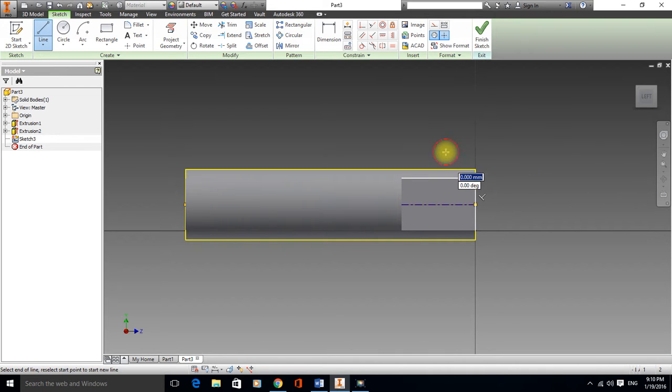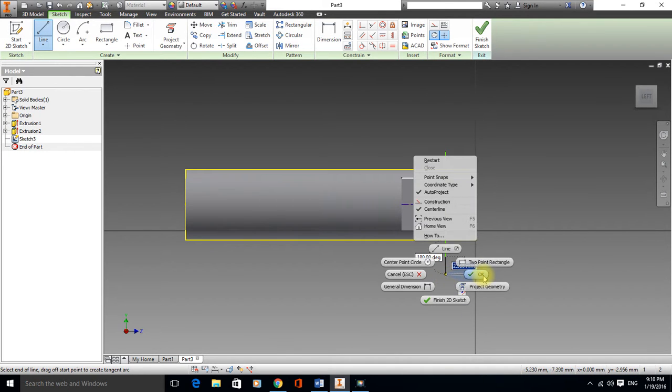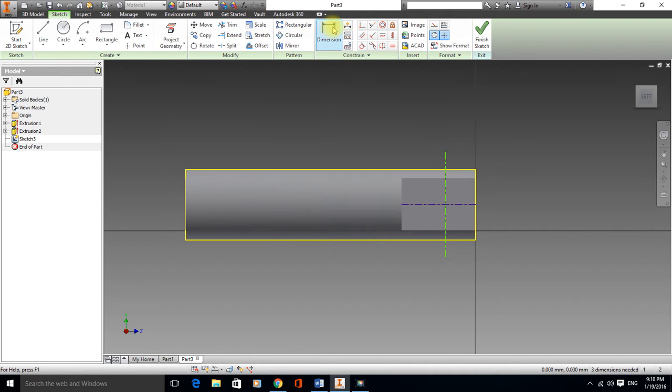Lastly, I just need a set of crosshairs for me to draw my hole, and for me to draw the arc that I need to put on, which I'm going to actually use to cut off the end shape. Right click, OK. This line is in the middle. Let's just dimension our other centre line from the edge of the job, 6mm. Let's move that across perfectly.